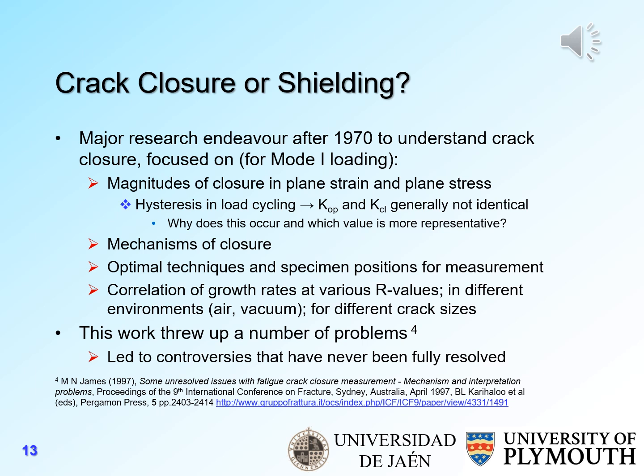And again, why does that occur and which value is more representative of crack contact? The mechanisms involved in crack closure, what are the optimal techniques and specimen positions for measurement, and correlating crack growth rates at various stress ratios in different environments and for different crack sizes. And that work has thrown up a number of controversies and problems that have never really been fully resolved, and I give you one reference to a paper here.